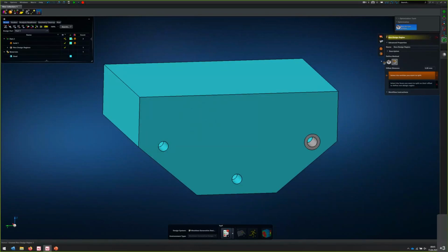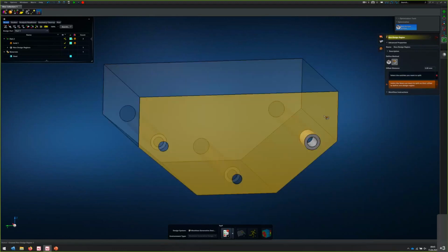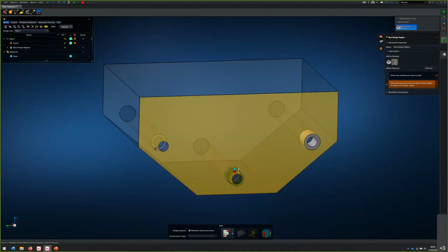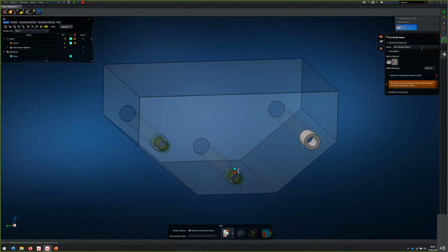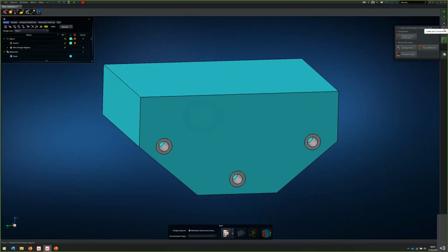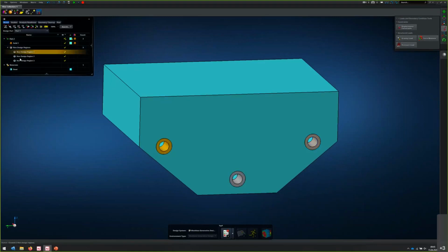As you just saw, you can click on the volume you want to select, and then on the surface you want to do an offset of, or you can also deactivate this and activate several faces so that they will be created at once. After defining these non-design spaces, which you can also see on the left-hand side in the model tree, all are here.